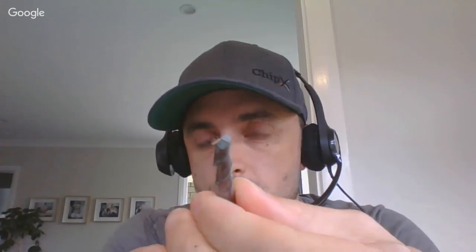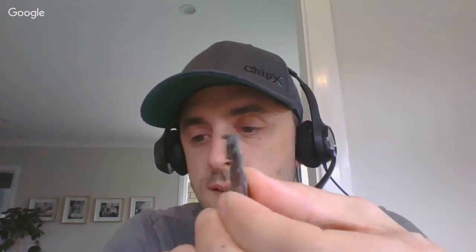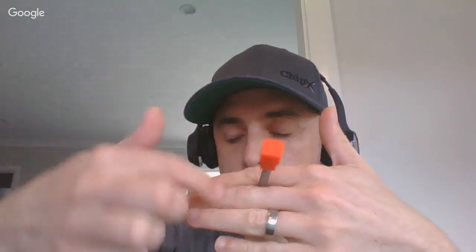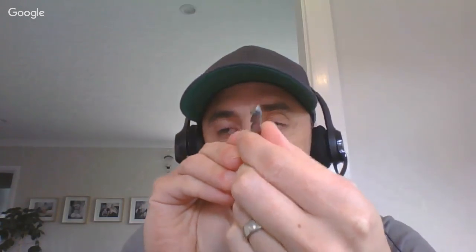Sure. Okay. So as that tool rotates, most of the time we're not going to be doing what we call full slotting. So if we were to drive that tool down into the material and cut along, engaging the full 180 degrees, the diameter of the cutter, the whole thing is cutting as it moves through the material.